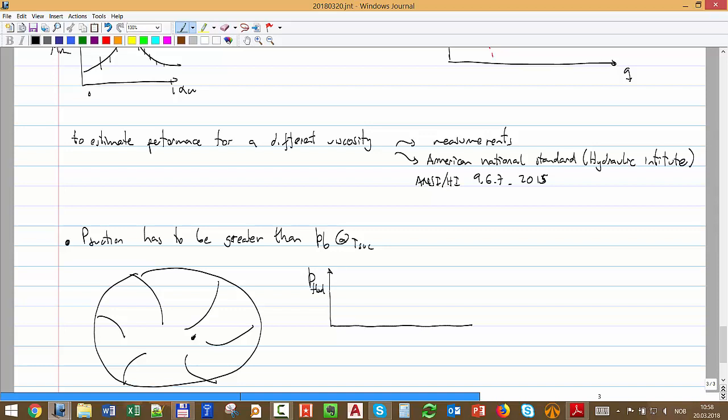And here this axis indicates distance inside the pump. Here you have P at the suction. It's going to go down and then it's going to increase. After you go through the first stage, let's say that's the exit of the first stage, then you will have again the same process, going down and increasing up, going down and increasing up.